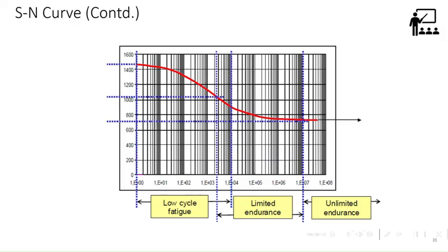But for designing any structure based on meeting certain requirements, where you have to have an ABD matrix to answer something, and you have a number of layers and orientations, which may be symmetric or asymmetric, in that case you cannot use a common SN curve available in the literature. It has to be generated for that particular system.